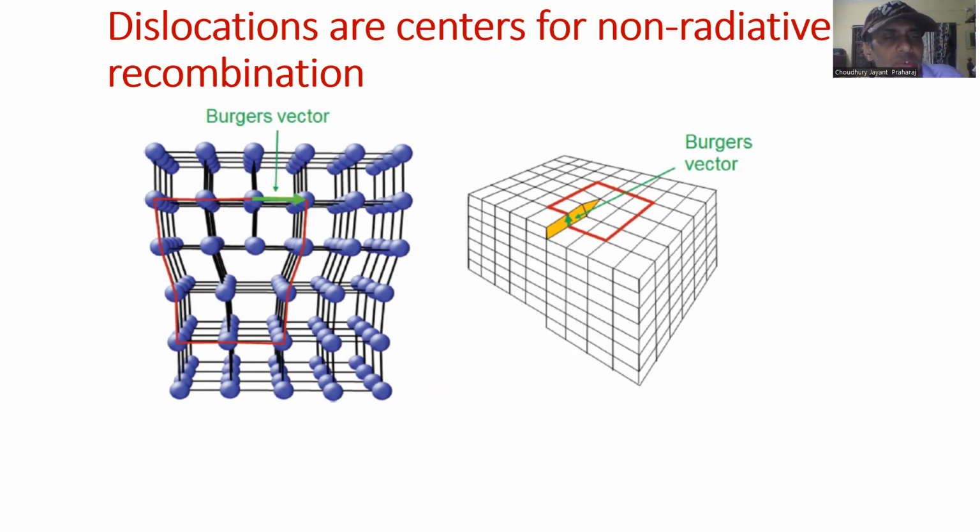So typically this indium gallium nitride material system has the wurtzite crystal structure, but here we show some schematic for example, an edge dislocation and then a screw dislocation in this material system. And we have the so-called Burgers vector characterizing these dislocations in this material system.